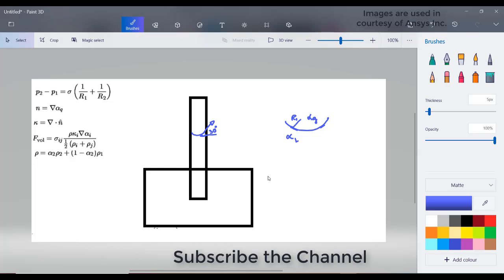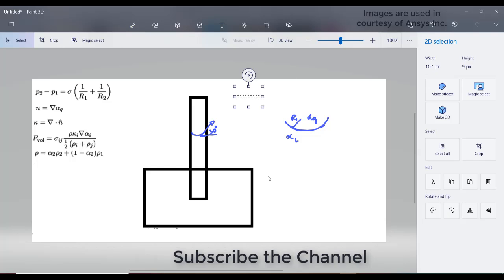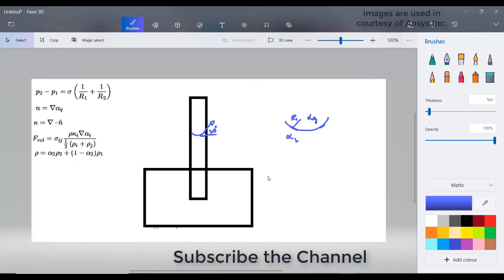So you can state that R1 equals infinity if it is a flat surface. If it is a flat surface, R1 is infinity, the radius would be at some infinite point, so this term becomes 0. Then there will be no surface tension force. So a surface tension force comes into action if and only if you have a radius of curvature.